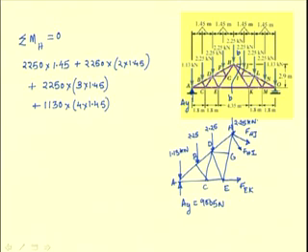The moment of the reactive force at A is a clockwise moment, so it is negative. The force is 9005 Newton as determined, times 1.45 into 4. So, this has to be equated to 0.